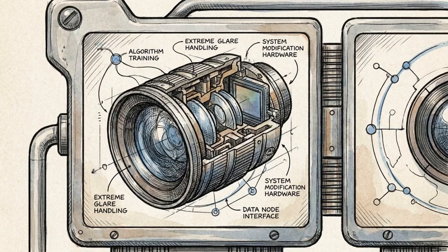To execute these strategies, engineers utilize 4 specific categories of modification defined by the standard. Quadrant 1 is system modification. This involves direct technical upgrades, installing high-resolution 120 decibel cameras to handle extreme glare, or training algorithms on vast datasets of rare edge case scenarios to improve recognition.